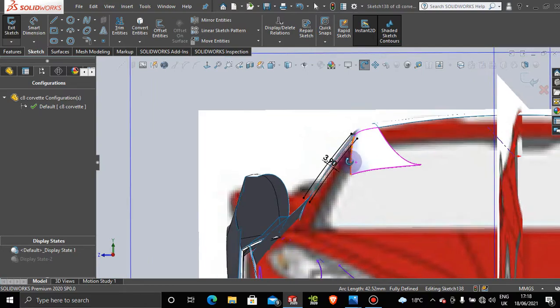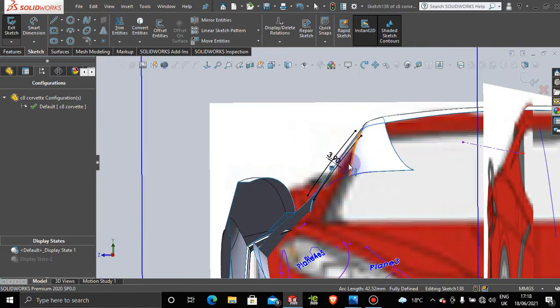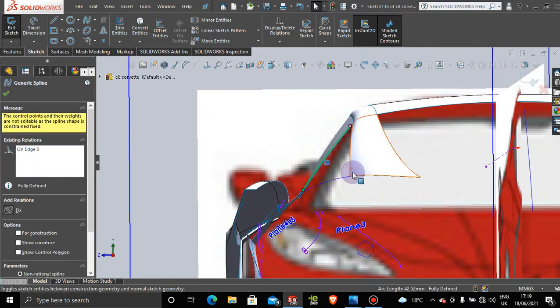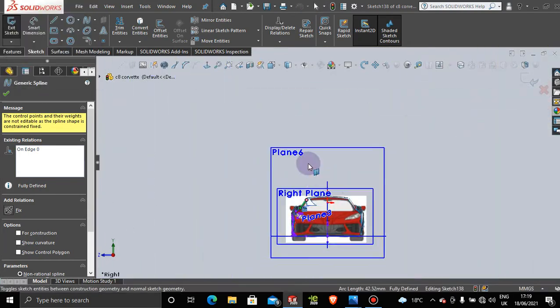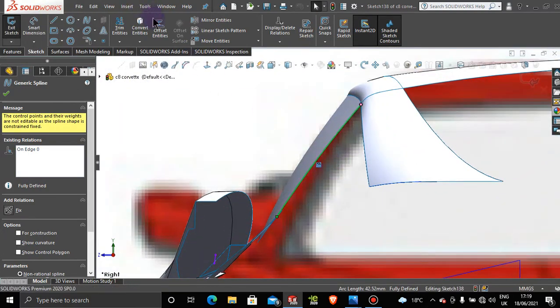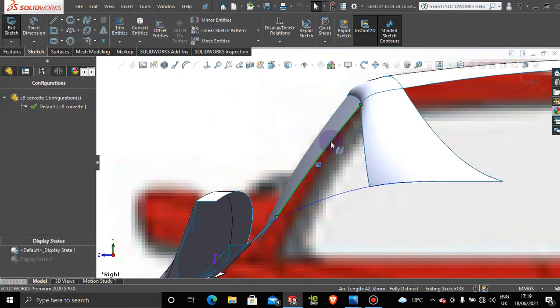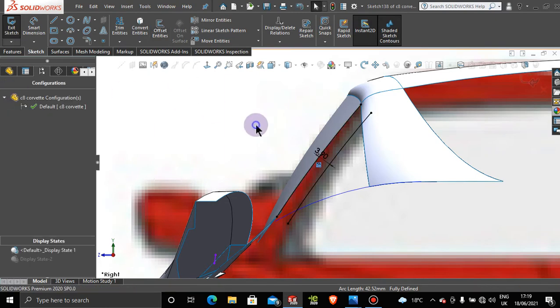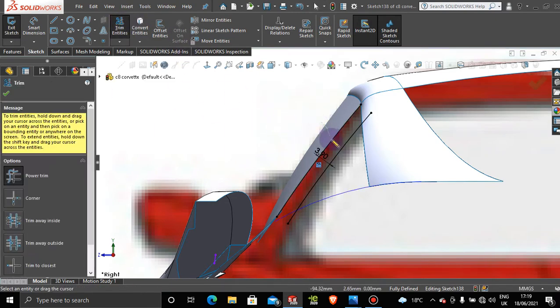So now, well, it reversed to the outside, right? Let's come to the back here quickly. So let's do that again. Let's come back to the sketch. And let's do an offset entities, and we want to reverse that to the inwards, right? So 3.9 millimeter. All right, and we're going to snip out the outside one, right?